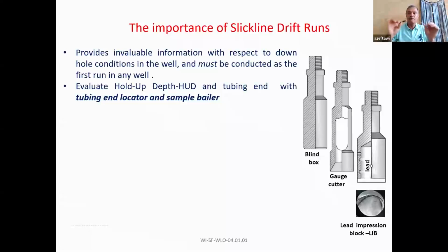This has to come from a third party inspection. Do not depend on visual inspection to decide if it is for standard service or for sour service. Never do that. It has to be done through certificates. What you do visually is to check that it has no tears, it has no cuts.